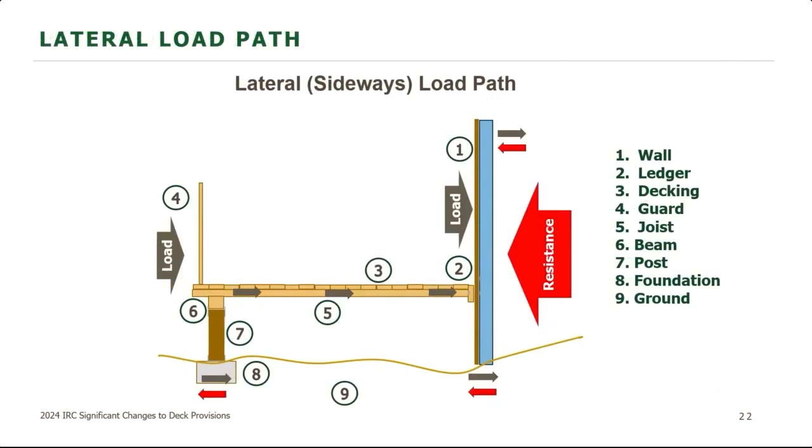And the same thing with lateral loads. On a deck, you may not get into a lot of loading from seismic or wind, but when you do, those loads have to make their way into the ground through the foundation. While it's not in the code itself, side sway from people moving on the deck is also a concern that would act in the same manner.